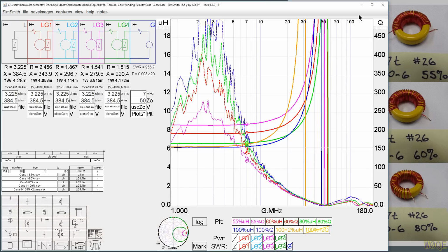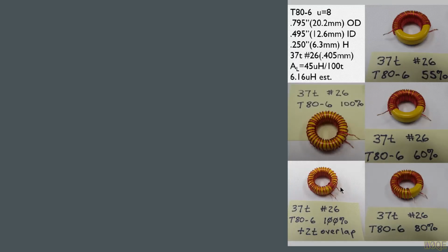So if we look at the mounting again, both this mounting are extremely fragile if you mount them on a circuit board. This mounting does not lend itself easily to a circuit board unless you put longer leads on it or you lay it flat. The 70 to 90% range leads you to the best mounting, and it gives you something that's actually a little bit stronger. So when you put the circuit board on this side right here, you mount these leads through the circuit board, you end up with some stability in both dimensions. And that's what I typically do when I do it.